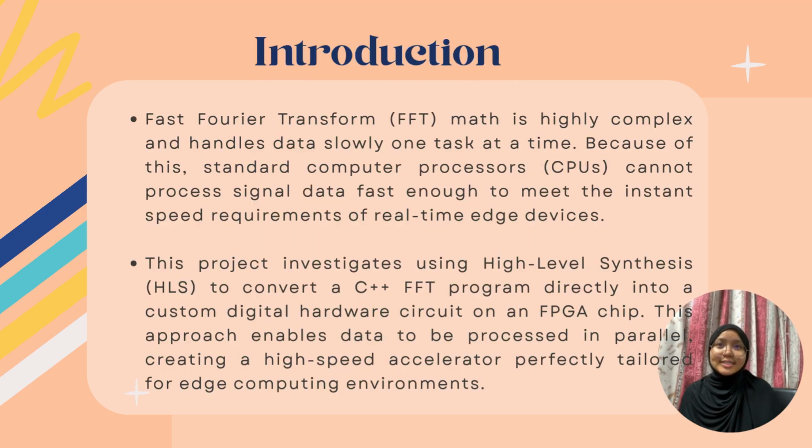We all know that standard CPUs are too slow for real-time signals because they handle heavy FFT methods step by step in a single line. So our team used high-level synthesis to turn C++ software into a fast parallel hardware circuit on an FPGA, giving us a high-speed accelerator perfect for edge devices.